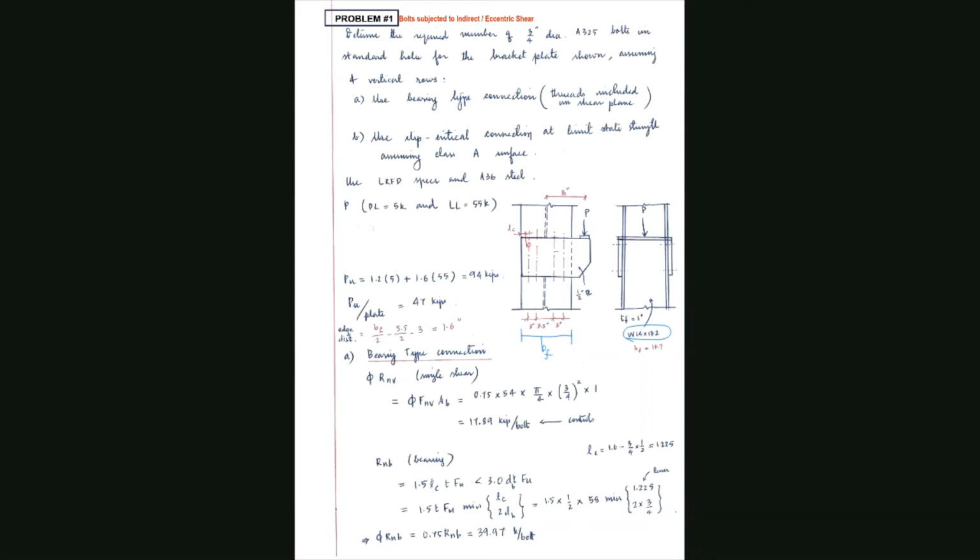So when you want this particular distance, which you call the edge distance, you have to find it by half of BF minus half of this minus 1.3, and the rest is the edge distance. I hope it is clear.